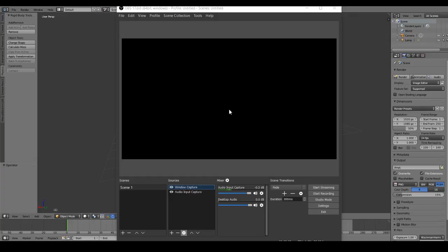This is our 3D view, and right now I'm clicking the middle mouse button, the scroll wheel, to move around this 3D view. You also spawn with a cube generally. I don't, I changed that in my default settings. But you spawn with a cube here, a little light, and this is your camera. We'll get into that more later. But this is what you come in with. And I'm right-clicking to select these, by the way.